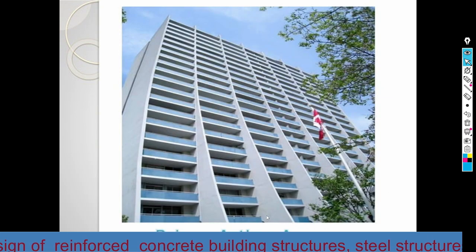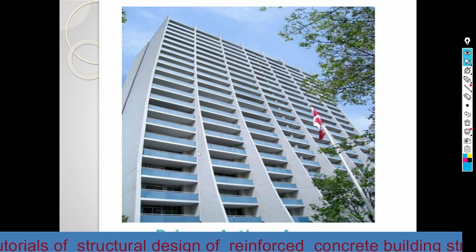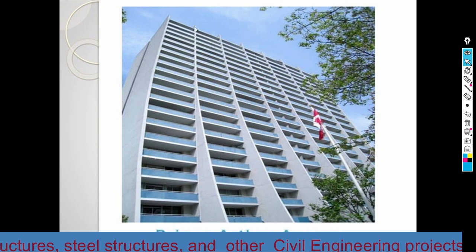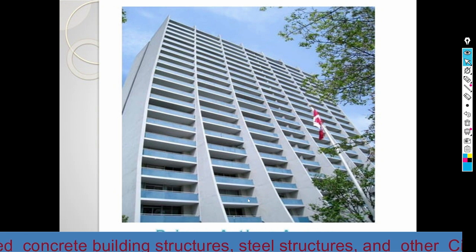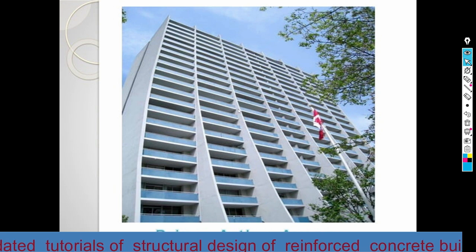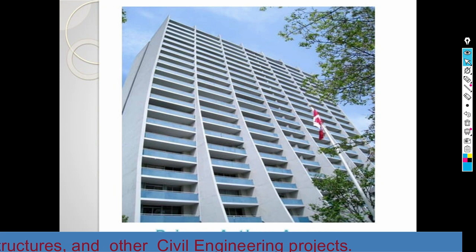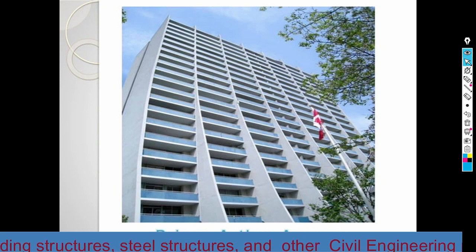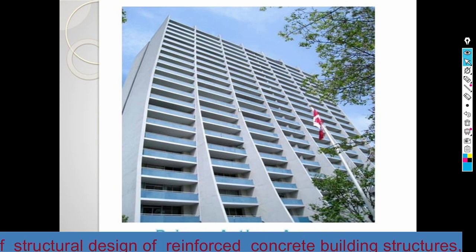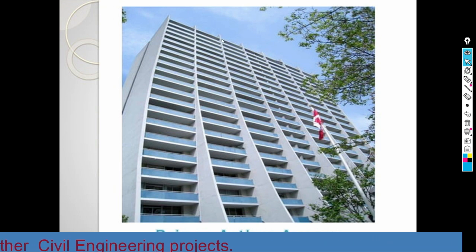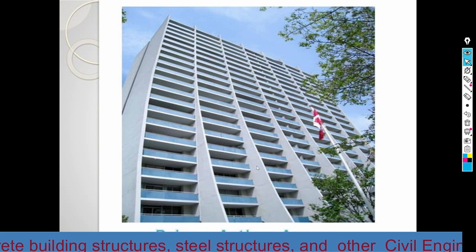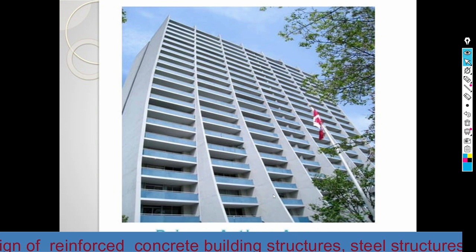just like this. Here the shear wall starts at the base of the foundation and it ends at the roof level. So we should not disconnect or stop the continuity of the shear walls through the height of the building. For example, if we extend these shear walls up to this point, and omit extending the shear walls up to the roof level, it is not recommended to use such kind of arrangements.